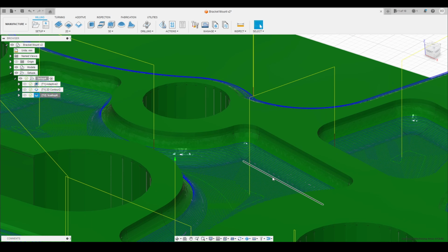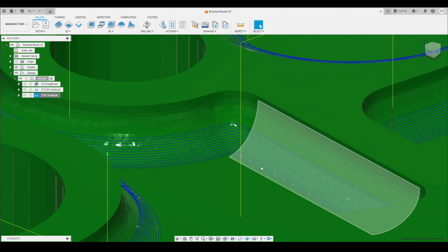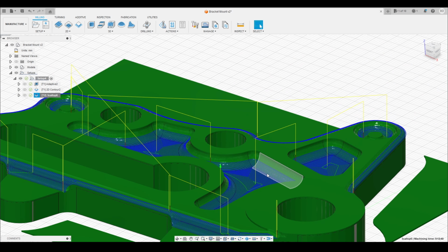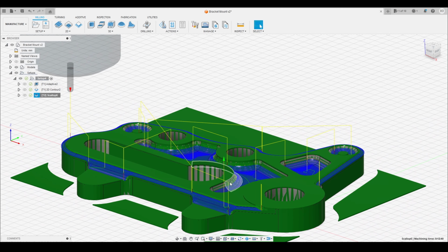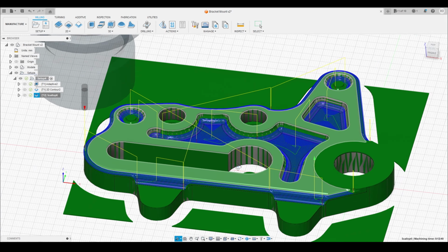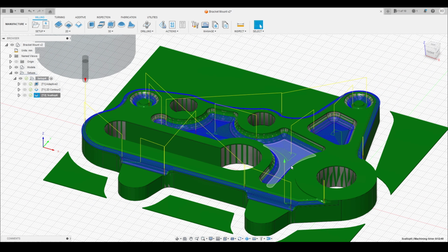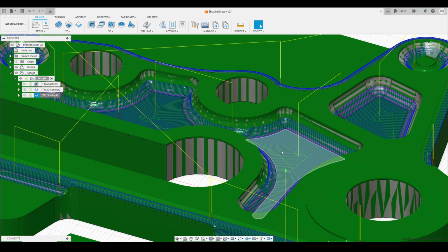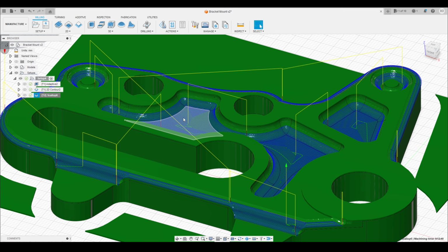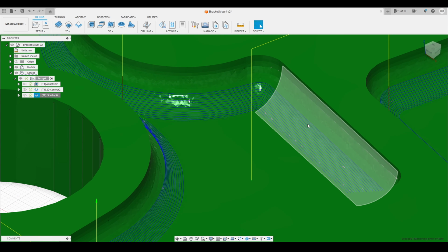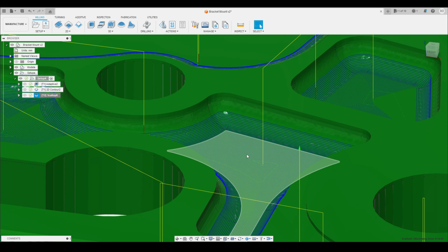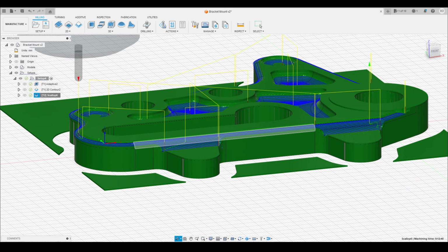You'll probably find that the cusping produced by the ball nose is almost imperceivable in the part when you take it off. You could also run this operation with a flat end mill if we were trying to eliminate this process down to using a singular tool, maybe not on this part, but a similar part. We could run the scallop operation with the same end mill we perform all the operations with. You're just going to end up with more perceivable stepping in here, but you can minimize that by changing the resolution. Nonetheless, it could be done.